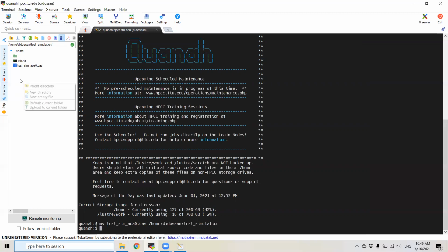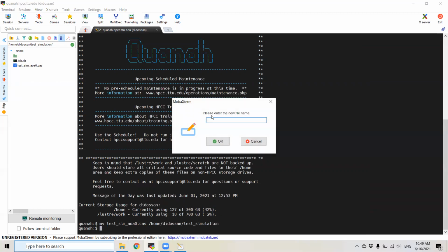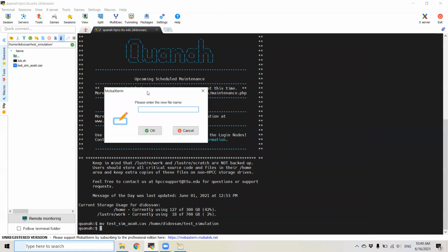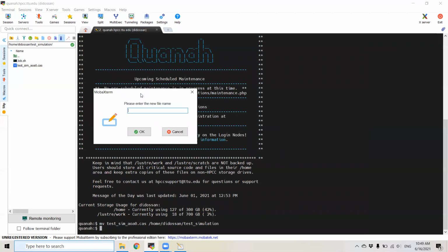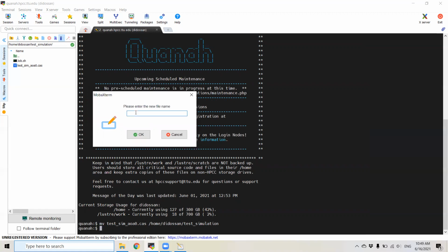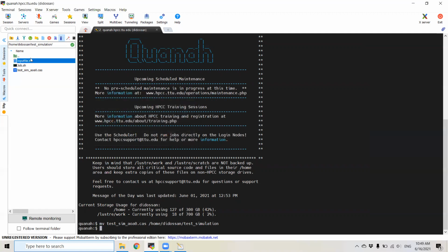I'm going to show you what an input file would be for a steady simulation, because that's what we're going to be focusing on in this video. I'm going to start as a text file, and then I'm going to change that to an input file, just because it's easier to edit the text file and then change the name.